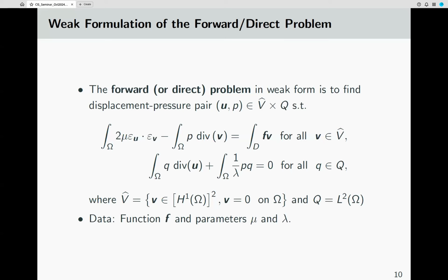Now, what we're going to have, there's not going to be a distinction between two different problems. What is a forward problem and what's the inverse problem? Forward problem basically means that you know the F, the force function, and you know the boundary conditions. This one is actually written for a boundary condition that's 0, that's completely pinned boundary. Your job is to find the displacement components, the displacement vector function. That's what we call the forward problem or the direct problem.